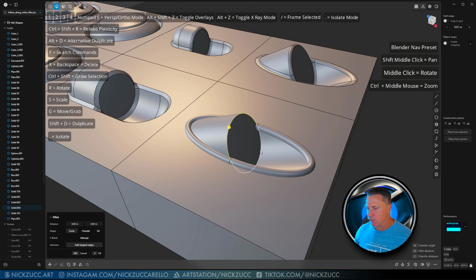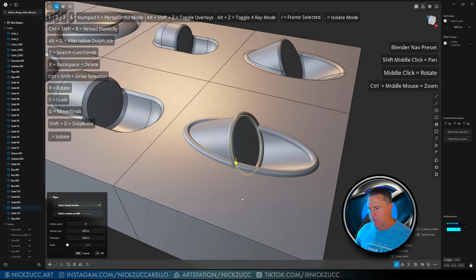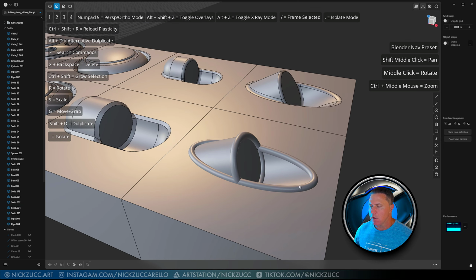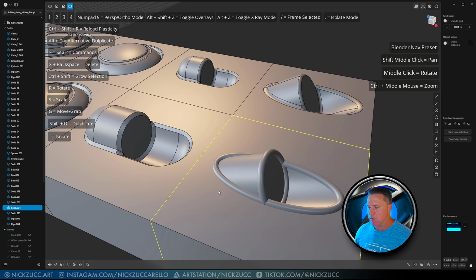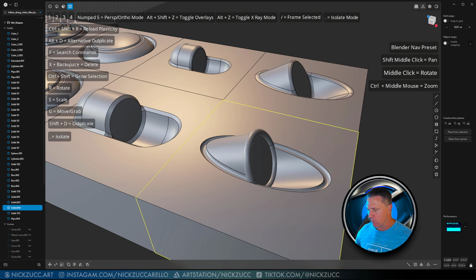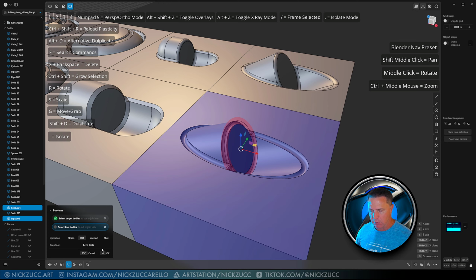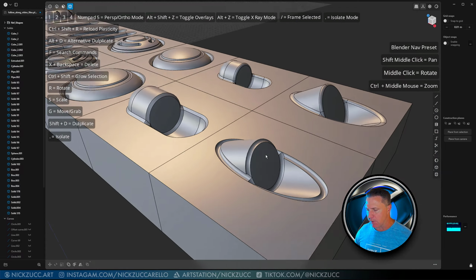And then now I'm going to select this curve and then this curve, and I'll do the same thing. We'll tap P. We'll set this to 0.02. And I'm going to tap B to make that into a new body. And we can right click and we can say OK for that. All right. So what's that going to give us? We can now take this, we'll tap 4 for this object, and we'll select this ring here and tap Q, and we'll do a Boolean. So we're going to get rid of that. Now we'll take this resulting shape, hold on Shift, select this, tap Q, hit OK, and we've just Booleaned off those different shapes that we've got on here.